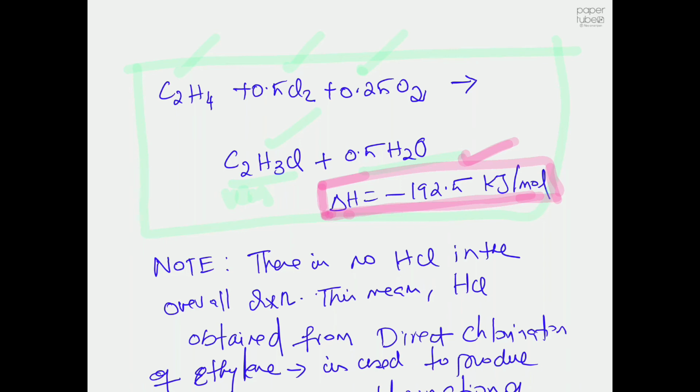That's because, in fact, that's our main objective. HCl was one of the byproducts during the pyrolysis step, and we use that byproduct in order to produce more vinyl chloride monomer. So that's why you don't see any byproducts in the product stream. Keep these things in mind. Whatever byproduct we get, like hydrochloric acid, will be recycled back in order to get more vinyl chloride monomer, which you see on the right hand side of this equation.